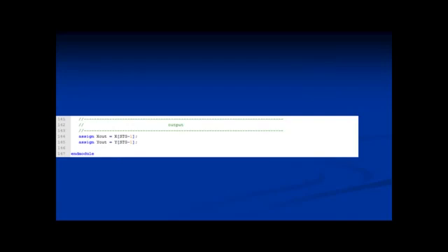The final lines of code merely assign the last stage of the pipeline's x and y values to the x out and y out signals. So that covers all of the Verilog code to make the coordinate. Next, we'll look at a simulation of the code generating a sine and cosine output.